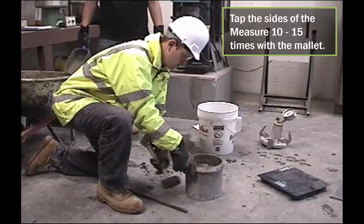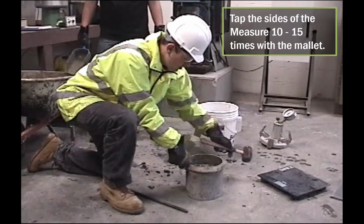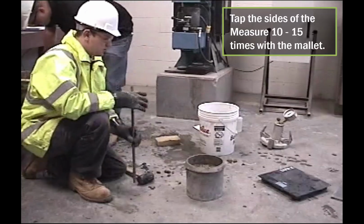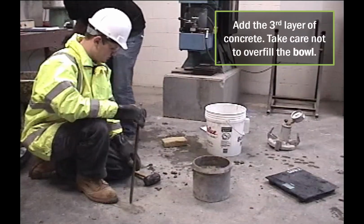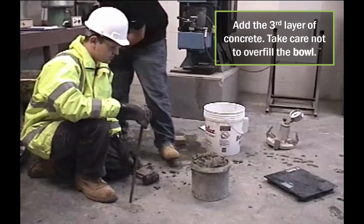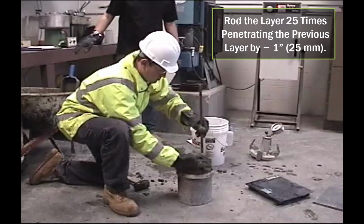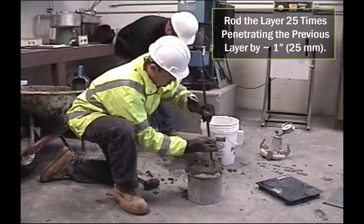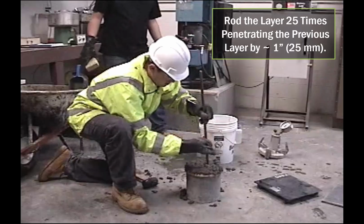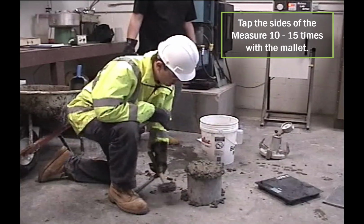Once again, tap the sides of the bowl 10 to 15 times with a mallet, using such force as to close any voids left by the tamping rod and to release any large air bubbles that may have been trapped. Add the third and final layer of concrete, taking care not to overfill the bowl. Rod this layer 25 times throughout its depth, penetrating the previous layer by approximately 1 inch, or 25 millimeters. Tap the sides of the measure 10 to 15 times with a mallet.